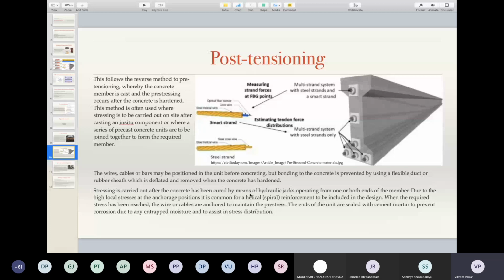So metro construction uses both pre-stressing methods. Inbuilt, the individual units are pre-stressed, so optimization of concrete is done. And on the side, there is post-tensioning which is done in many of the members, so that you have higher strength, and they can be adjusted over a period of time. With age, you need a slight adjustment in the tensioning also, so those adjustments can also be done.